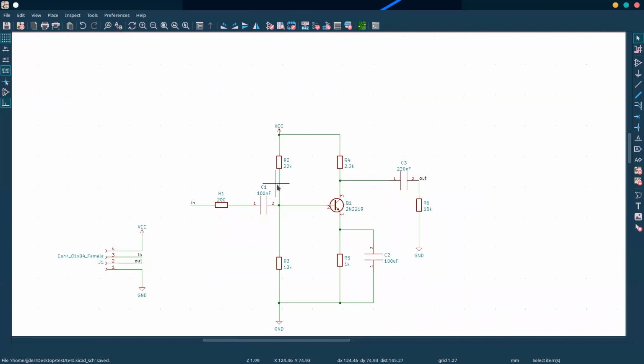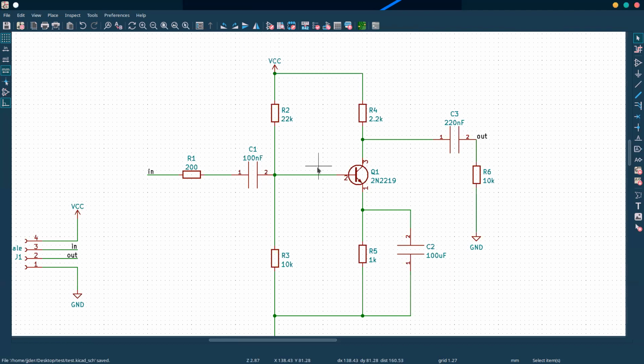Is each resistor labeled uniquely, or is it by value? Each resistor is unique. Like R1, R2, R3 could all be 200 ohms. In this schematic, we know that our resistor is 200 ohms. It looks like a little rectangle, but in reality there are a million different kinds of 200 ohm resistors, so you have to tell KiCad what you want that resistor to look like.